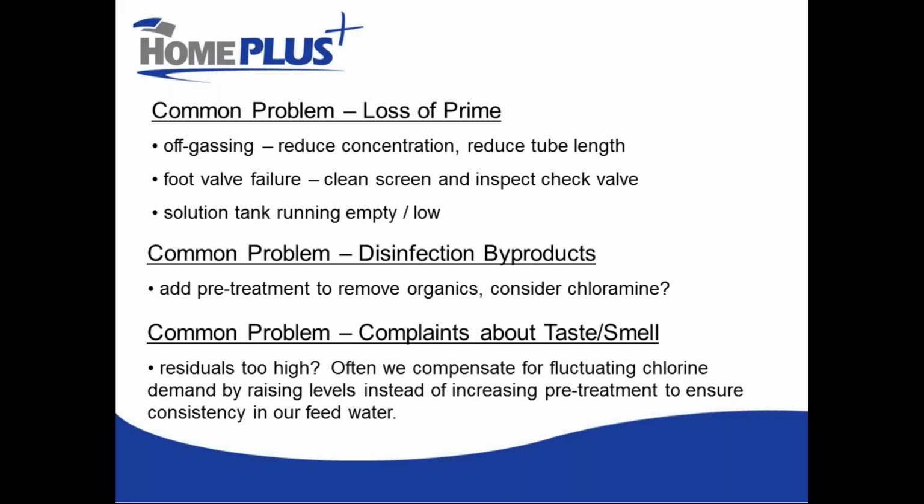Some of that can come in the long term through infrastructure replacement, pipe replacement, especially if you have old cement asbestos lines that might have years and years of mineral buildup in them and so on. Replacing that with modern pipe in better condition might make it easier to get the residual out to the end of the line.